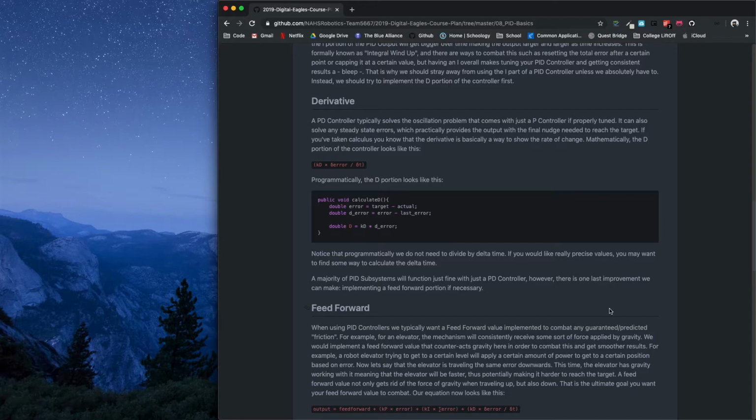So if the feed forward value is causing the slide to just stay still, then that's absolutely perfect in what we're looking for. And typically you can get away by just making it 0.1. At least in my experience, that's always worked. And so I would recommend just starting with 0.1. Of course, the max value being 1. And so the feed forward basically accounts for that gravity, right? That's what we're combating here.